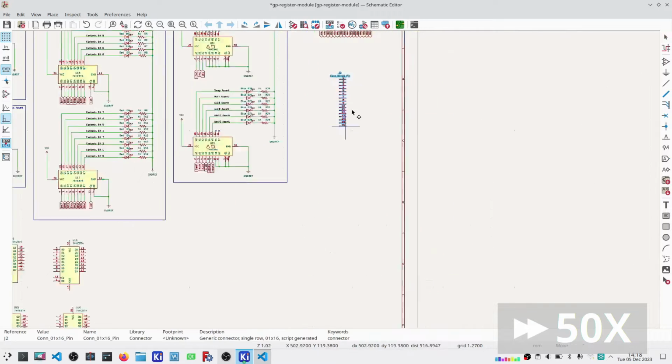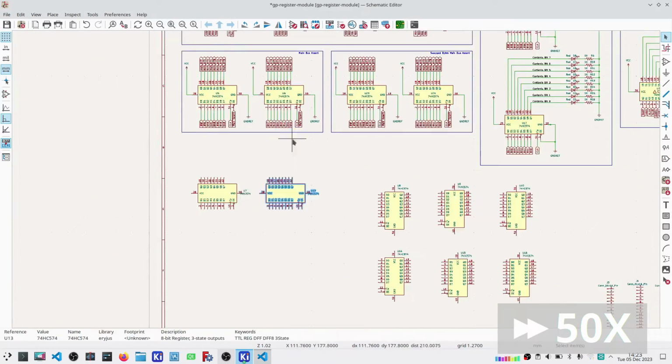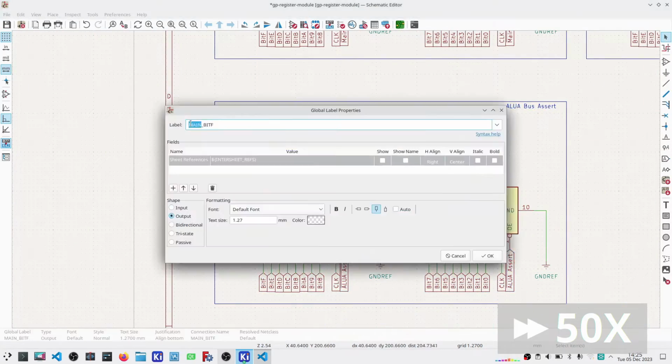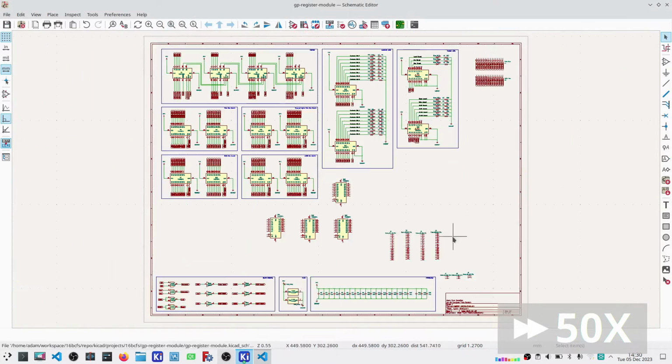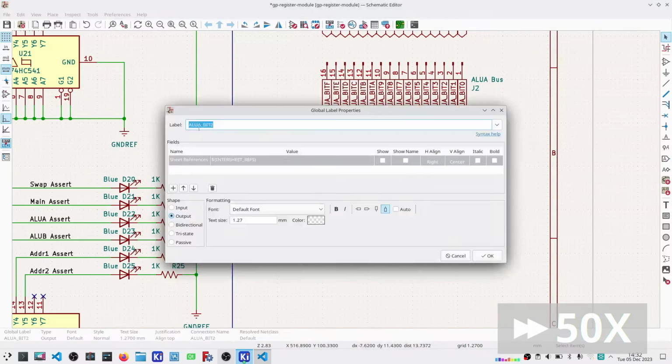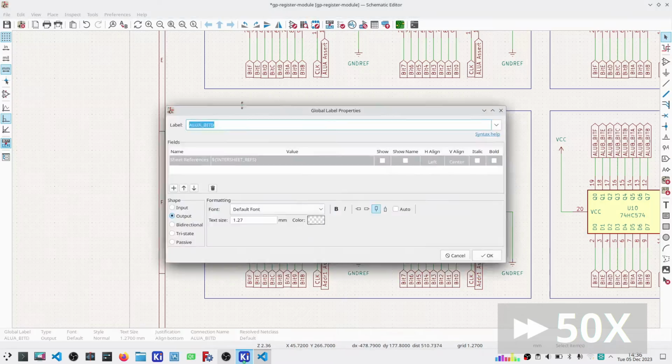Now I am going to bound the clock signal by ground signals so that there is a ground coming in on either side of the clock. That's my intention. And so I'm using 16 pins wide in order to handle those signals. Prior I had 10. I'm going to end up with 4 or 5 or so that are unused, and they'll all just be tied to ground.